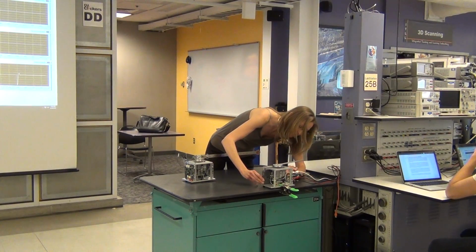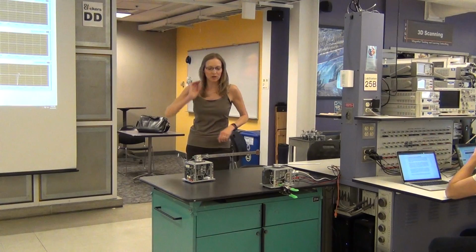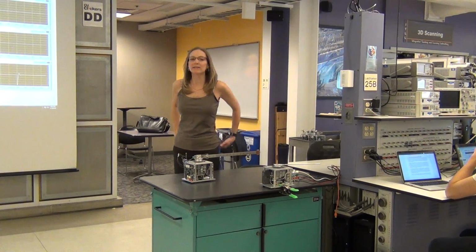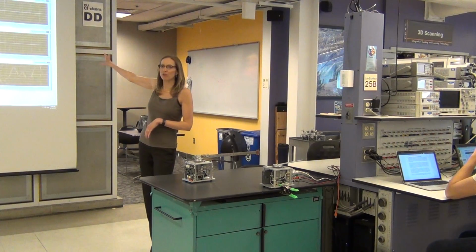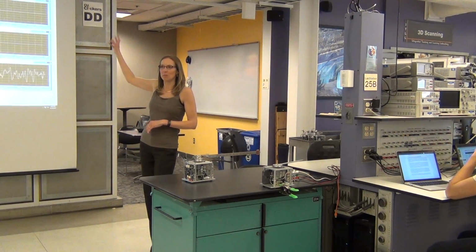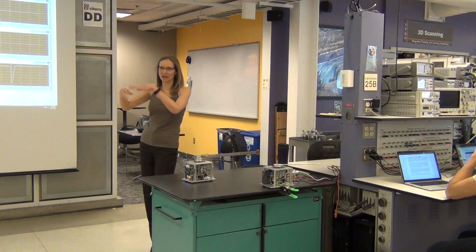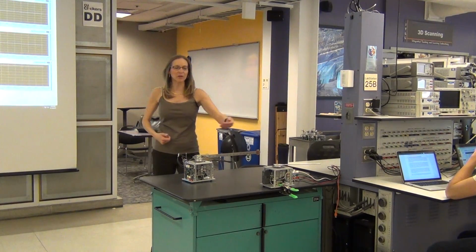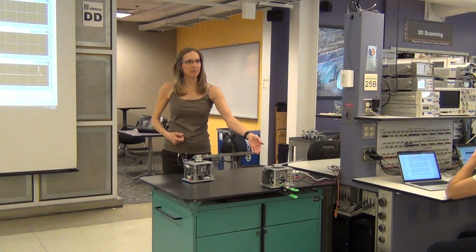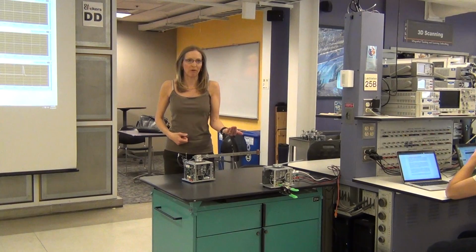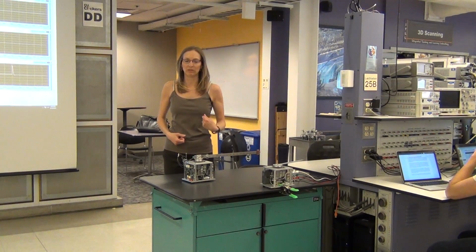All right, now we'll plug our ground station back in so we can send new commands. Another reason why it's important to shut it down properly. Just closing out the LabVIEW program and Xing it out might leave the controller on there. It's just going to keep running until you power cycle, because we programmed in for it to restart from 0 once we power cycle the unit.